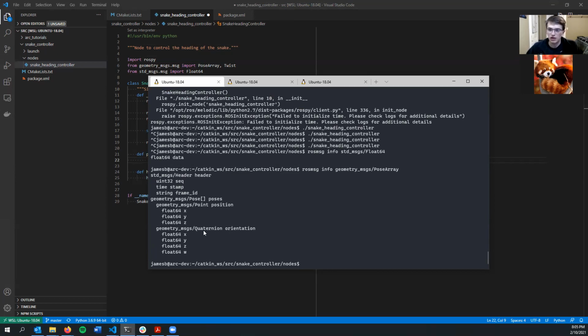So aircraft normally use roll, pitch, and yaw, or if you're familiar with drones, you know those terms. You can roll, pitch, and yaw, and it spins you about the X, Y, and Z axes respectively. One of the bad things with that representation is that if you want to point straight up, there's an infinite number of roll, pitch, and yaw commands, or maybe not infinite, but at least multiple ways that you could represent that. That leads to some issues whenever you're doing things with computers. So that's why people have the quaternion instead.